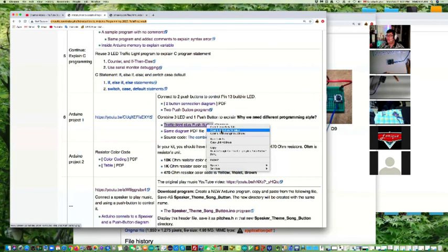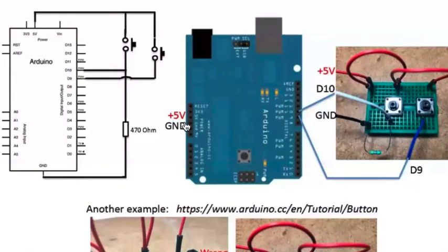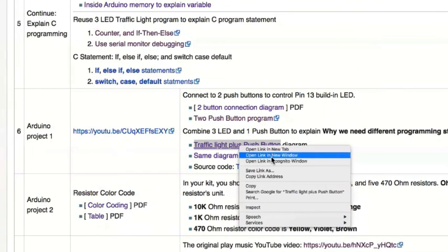Enrique, do we get the 5 volts from the power side? Yeah. So remember I showed you this one here, on the picture? This one is Vin, ground, plus 5. You can connect this plus 5 into here. Why are we doing this? Because next time we are going to explain combining